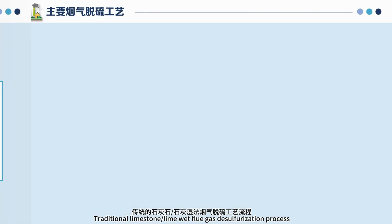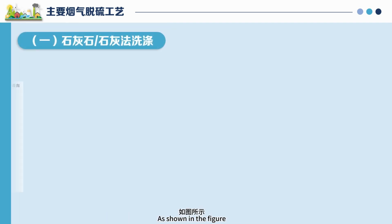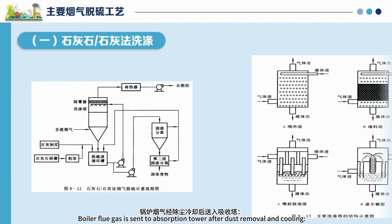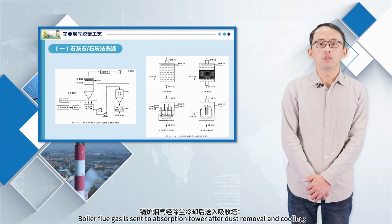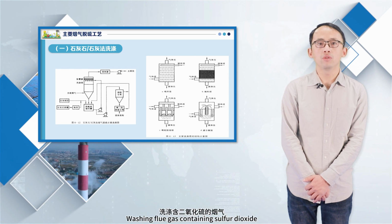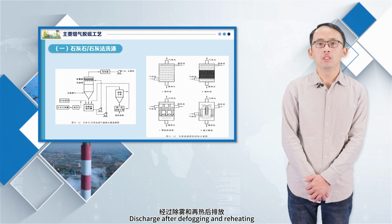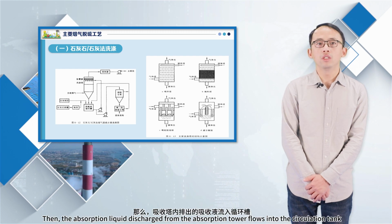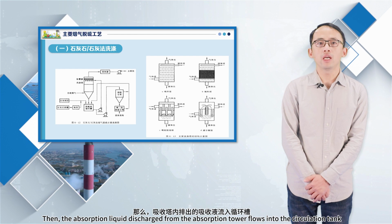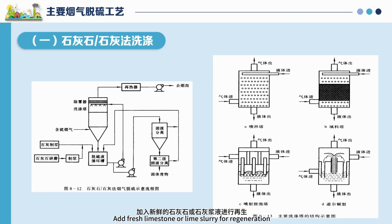Traditional limestone/lime wet flue gas desulfurization process. As shown in the figure, boiler flue gas is sent to the absorption tower after dust removal and cooling. The prepared limestone/lime slurry is used in the absorption tower to wash flue gas containing sulfur dioxide, which is discharged after defogging and reheating. Then the absorption liquid discharged from the absorption tower flows into the circulation tank, where fresh limestone or lime slurry is added for regeneration.